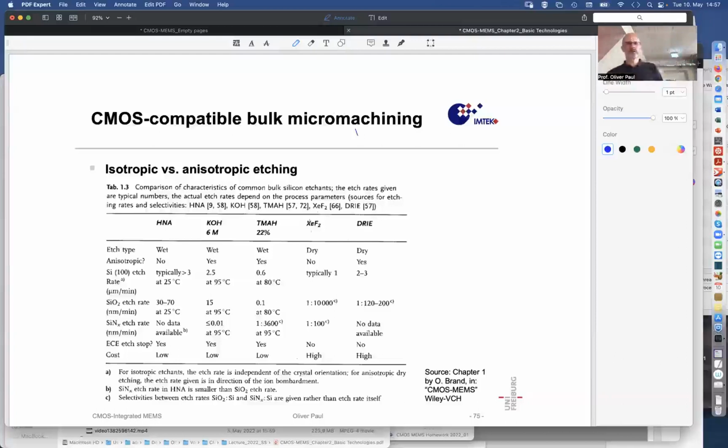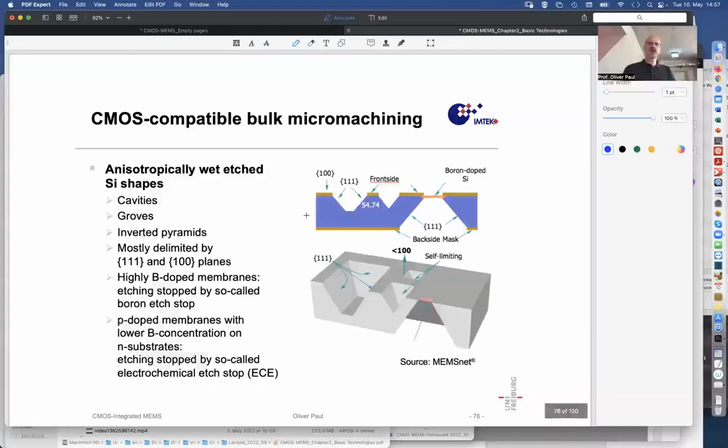For xenon difluoride, you need a deep reactive ion etching, you need technical infrastructure because xenon difluoride is highly reactive and you should not release it from the system. So this needs pumping and very good mechanical components. And deep reactive ion etching needs, of course, an ionization source for the gas that it uses. So that's a complicated machine that easily costs $1 million.